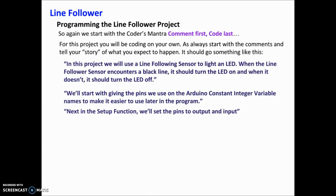Now in the setup function, we're going to set some of the pins to input and some to output. Again, we want to set the LED pin to output because we want to send out a signal to turn it on. But the pin that's coming in from the line following sensor, we want to set that to input because we're going to be sensing information off of that pin.